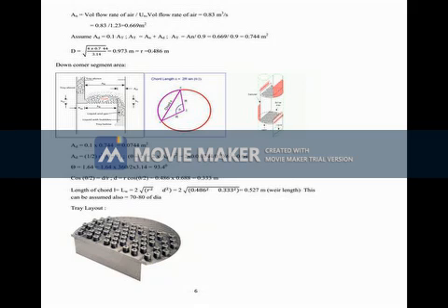You don't know what Xn is. The quantity is also not known. Here, since the amount of liquid is not given, you have to assume a minimum and then take 1.5 times the minimum and find out the actual amount of water. The slope of the equilibrium line is given as 1.68. Now you have to find the minimum amount of liquid required.